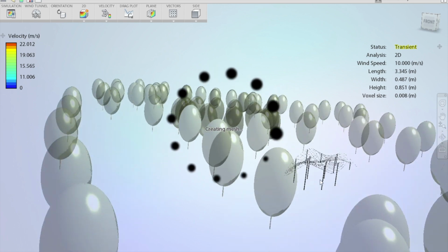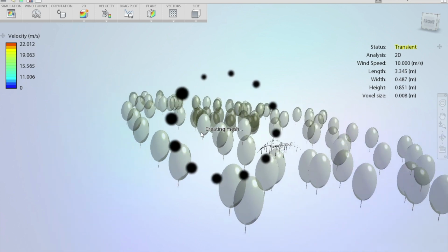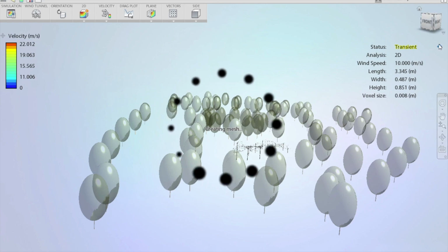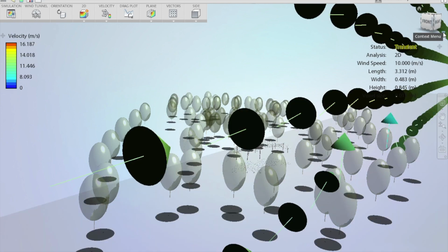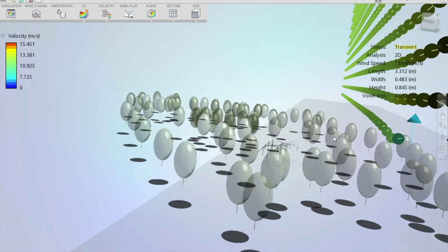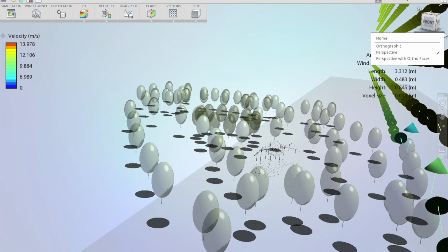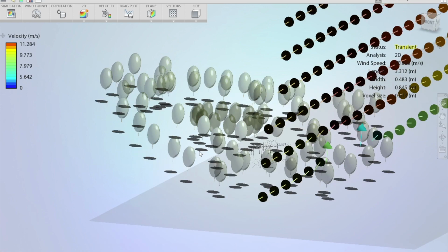Afterwards, I would want to check the wind tunnel settings. But before that, change your model's camera view from perspective to orthographic. From the top right corner, there is a small button underneath where the 3D box is located. Open the drop-down context menu and change it from perspective to orthographic. This will make it easier for you to adjust the following settings.